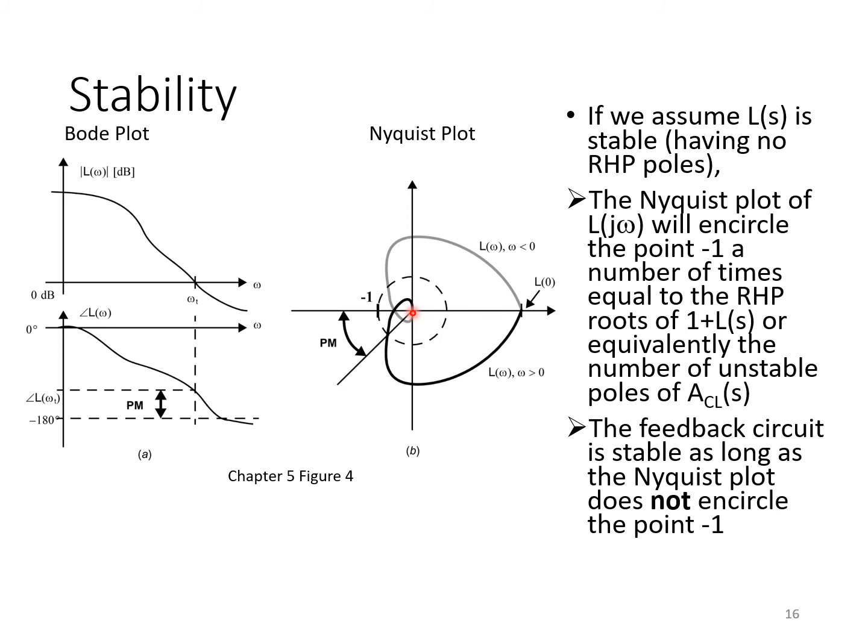So this is the case for the sort of simple feedback amplifiers that are going to be our initial focus here. Moreover, it's really a very unusual case where L is itself unstable. That's not the same as the closed loop amplifier being unstable. In the vast majority of cases that are of interest to us, we're beginning with a response for L that is itself stable.